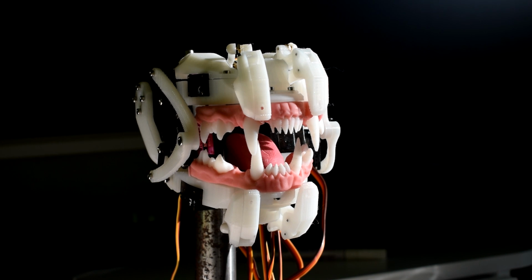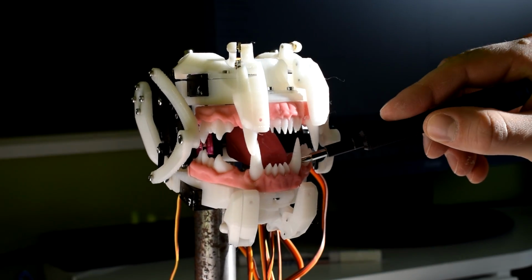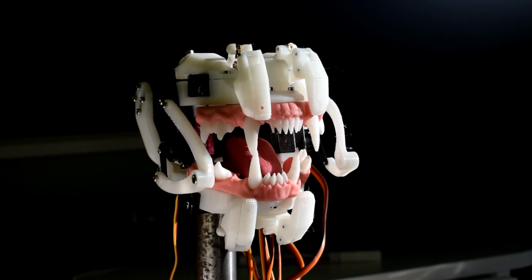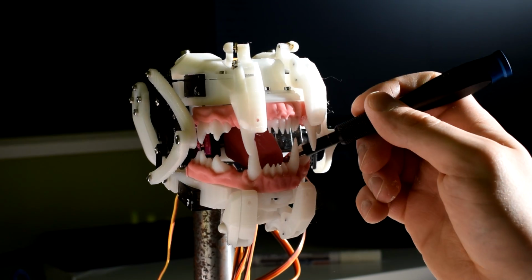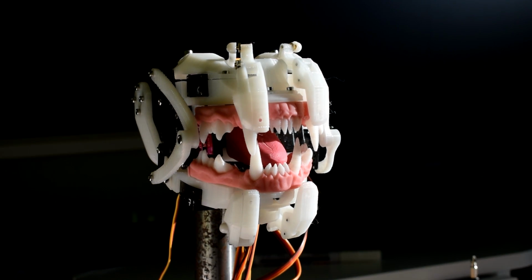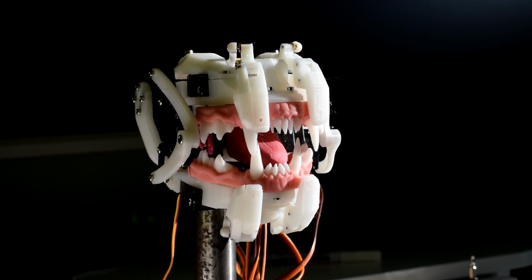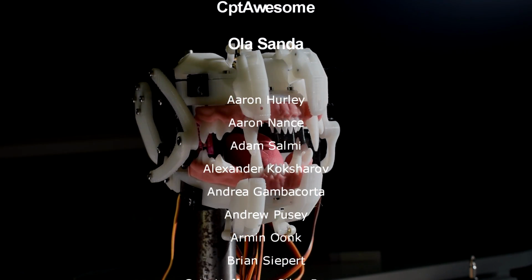So what I would propose is that the best solution would be to use motion capture on the face for mouth and jaw movements, which can then be directly mapped onto the motors of the animatronic mouth. But then simultaneously, if you had a program that listens to an audio input, corroborates with the motion capture data, and makes a best guess for the phoneme being spoken at that moment in time, I reckon that'd give an absolutely fantastic lip syncing to an animatronic mouth.